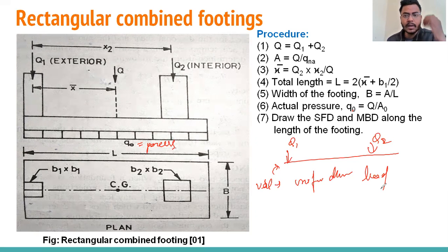or we can draw a bending moment diagram, so that we can calculate the maximum or minimum bending moment and the bending moment at every cross section wherever needed. So we have to calculate the UDL. Simply, the UDL is q0, that is the pressure, working in the L direction, multiplied by the length perpendicular to this figure.